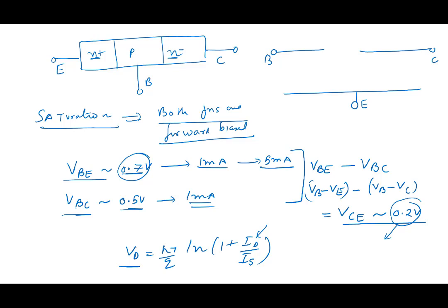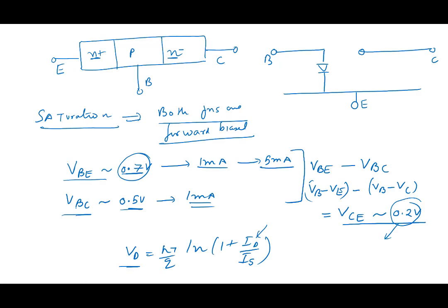At least the same diode is still there, right? Same diode. I'll put it here. Between collector and emitter, what should I put? What are you finding between collector and emitter? A voltage source of a value about 0.2.